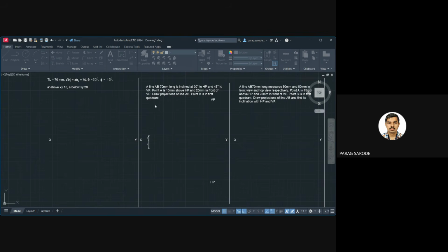Look at this now, 14.11. What was the default? Comma. Okay. Now click on OK. So I'm removing decimals for a moment and clicking OK. Set Current will change whatever we have drawn so that it adheres to these settings. Close. You can see there is an increase in the font. Now, whatever annotations we have written, we will produce on the side.